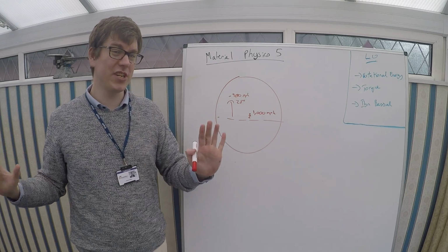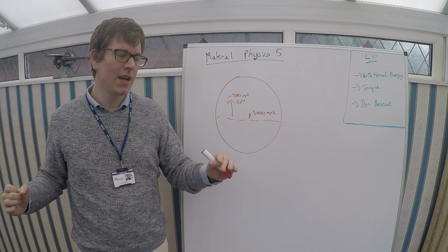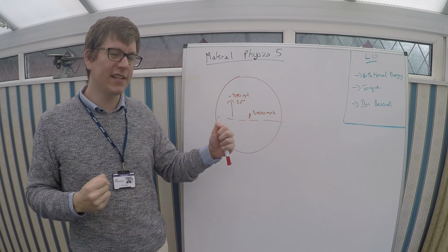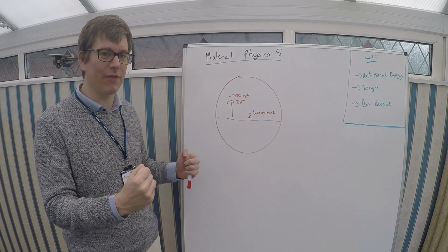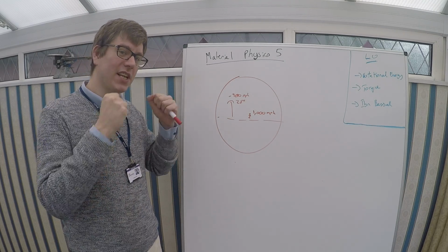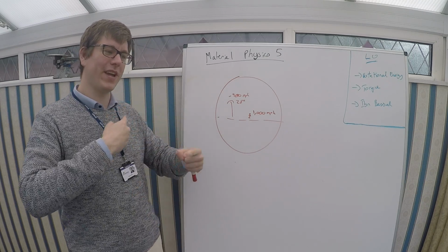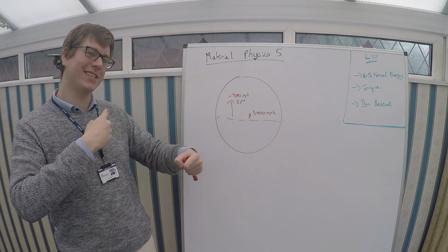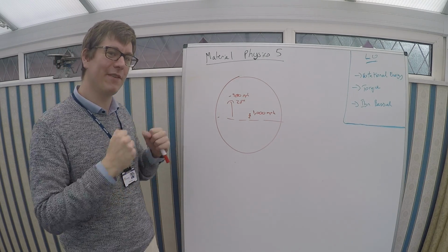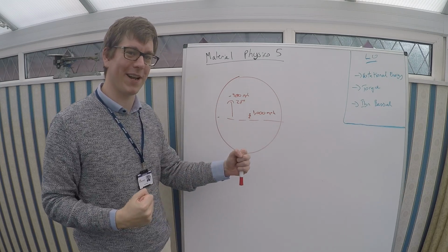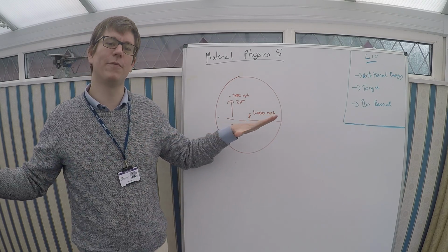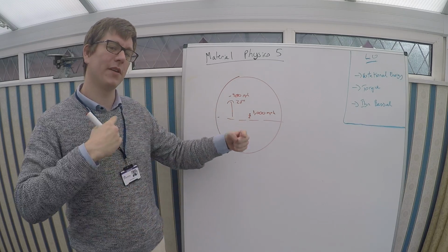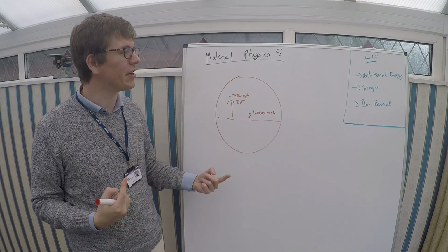And if you're making a machine that's a little bit naff, and the force going in is a little bit inconsistent because maybe your pistons aren't always firing and what have you, if you use them to accelerate the flywheel and then you draw the energy off the flywheel, you can get a nice consistent source of energy, even if the forces going in are a bit all over the place. And this allows you to create much, much more level forms of energy by using the flywheel as a place to temporarily store the energy.